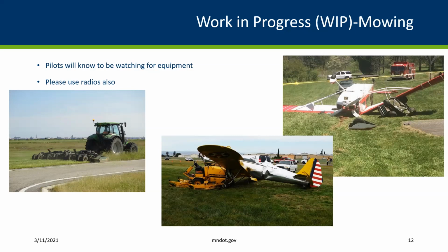So a lot of times when you see the tail draggers taxiing out, they kind of S-turn as they're going along so they can see around that engine cowl. But when they come in to land, they're trying to keep the airplane straight. They can't afford to be turning back and forth. So they touch down, and once they touch down, that blind spot's there, and they just didn't see these mowers at all. Very unfortunate.